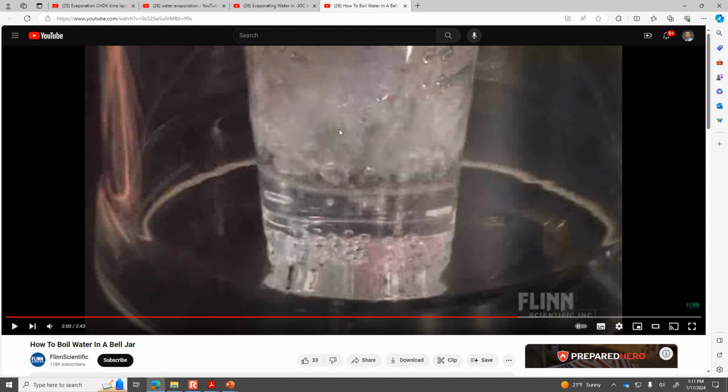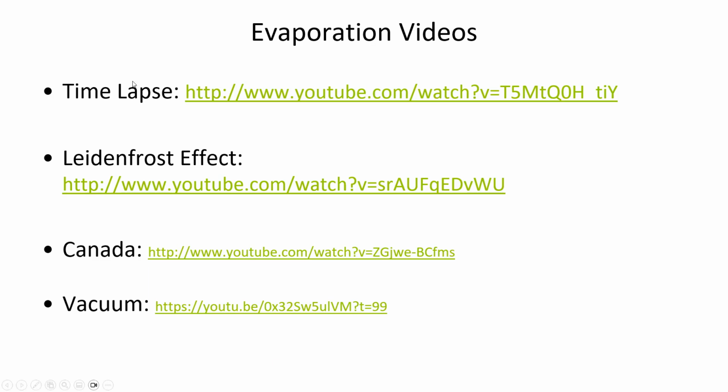If they have very high velocities, then the pressures can be reduced so that the pressure is as low as the vapor pressure of the water, and then cavitation can cause damage sometimes to these high velocity water pipelines. So these are all just illustrations of different things that cause a transition of liquid to vapor.